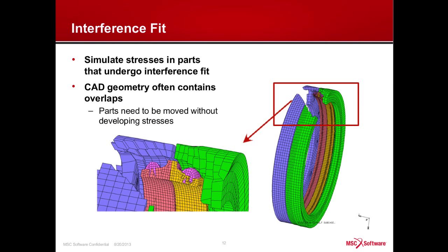Overlap during analysis, as you can guess, could lead to either penetration or even non-detection of contact. If the penetration is too deep, the solver may not even detect contact very well. And this means incorrect contact forces and incorrect results overall. So with Marc, you can remove this type of overlap without accumulation of stresses, and users don't have to spend time cleaning up this geometry, as it is automatically taken care of by the solver. And here is one example.